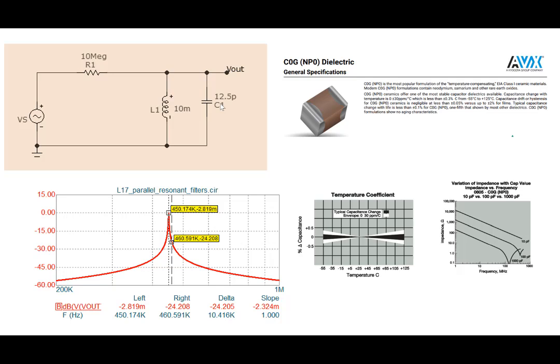So one uses special capacitors. For example, you can see here, these are capacitors which are called NP0. They are temperature compensating capacitors. The capacitors and inductors have to be as much as possible independent of temperature. But despite taking all possible precautions, you can see here the percentage change in capacitance as a function of temperature.